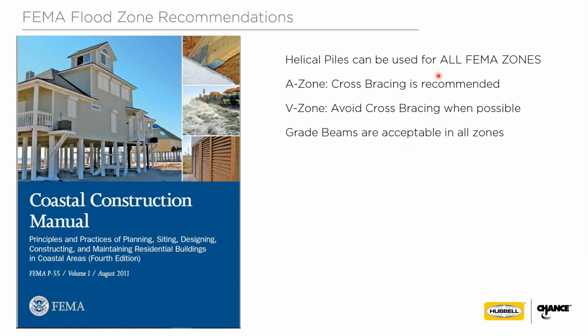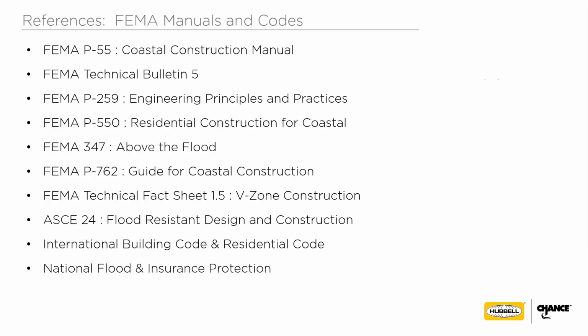And primarily, you would look at helical piles for elevation of structures like this when it's not possible to elevate the structure by moving it from the site or off to the side and then installing piling afterwards. If it's not possible to do that, helicals are a great choice. So we'll talk a little bit about those A zone and V zone requirements when it comes to the FEMA recommendations when it comes to flood zones.